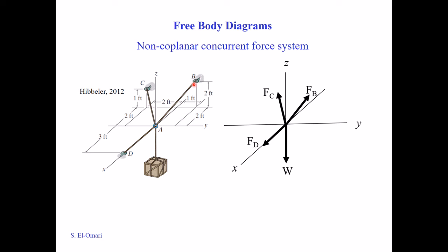You can then use these dimensions in representing the forces in Cartesian vector form. Remember, when you have dimensions like that, what method? Remember, we said there are three ways to represent a force in Cartesian vector form: either direction angles, and we don't see any direction angles here, or projection information, and we don't see these two triangles either, or position vector. Whenever you see dimensions like that, of coordinates, then you know that you have to work with a position vector. We'll talk about this in the next sessions.